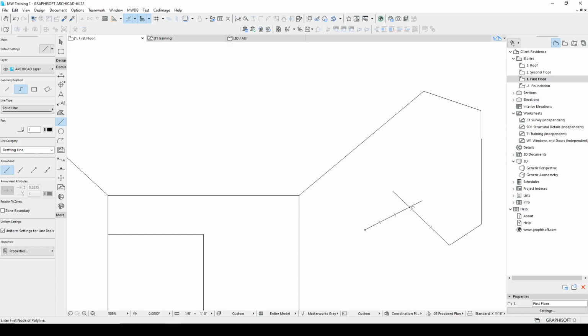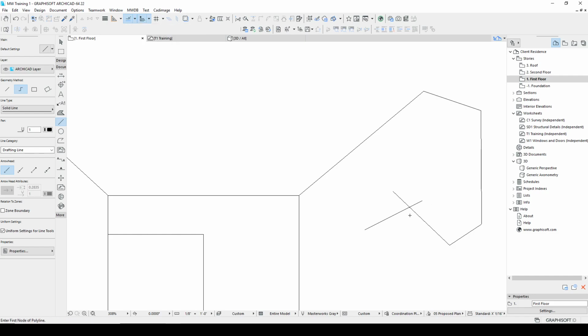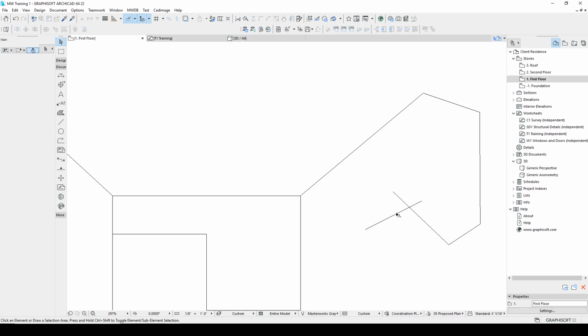I don't have to trim this. I don't have to do artificial construction geometry. I'm able to just do this on the fly. And I change these up here. Now you notice I have between nodes as an apostrophe; shift apostrophe, which is actually quotation marks, is my way to remember how to switch these back and forth with the keyboard. So we'll go back to between nodes, which then puts the thirds from the endpoint to the endpoint, which is a really important feature. So we've covered a lot of things here.